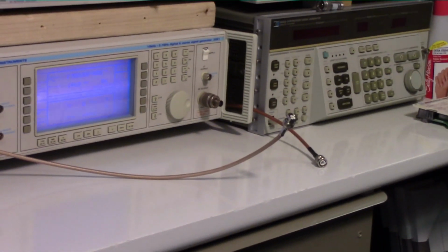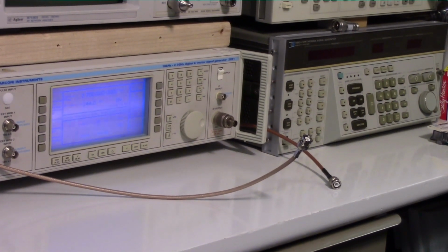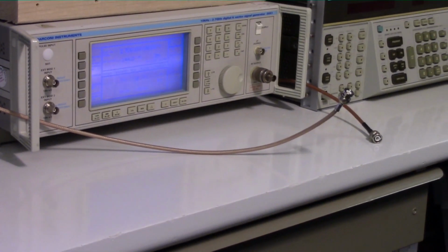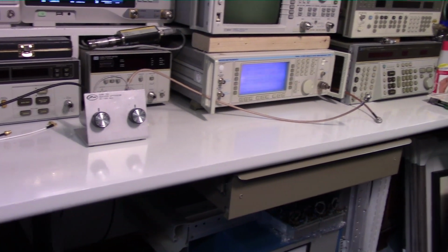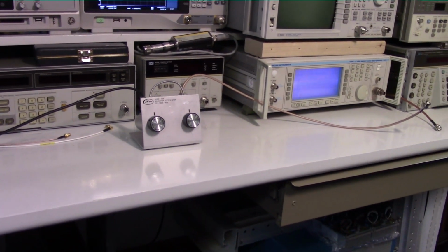And it doesn't take a lot, for example, for a strong signal, like let's say I had a minus 20 or minus 30 dBm signal coming out of the generator, and if I had my coaxial cables all lumped up nearby, and I had this output coaxial cable nearby these other cables, there could be a lot of crosstalk between the cables because of the limited shielding effectiveness of the coaxial cables.